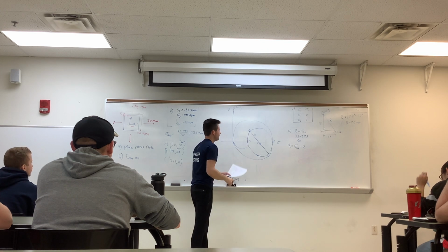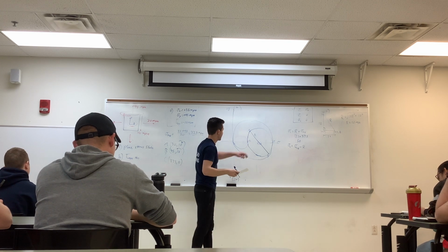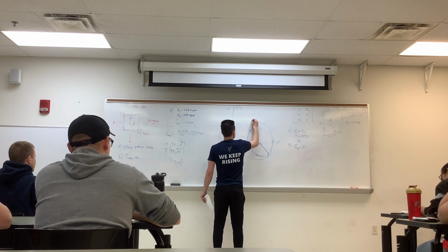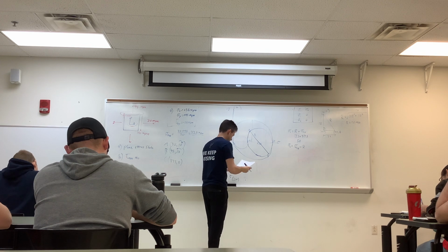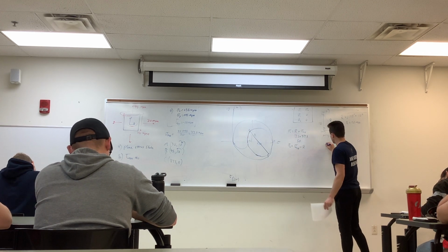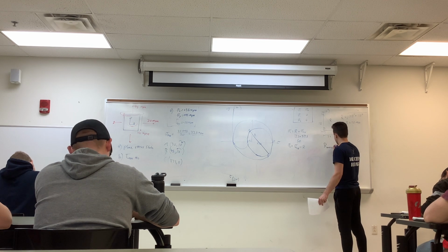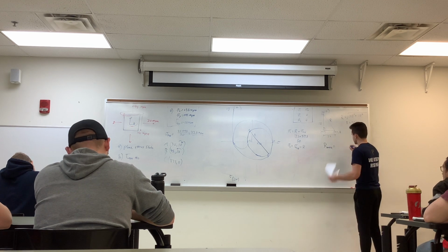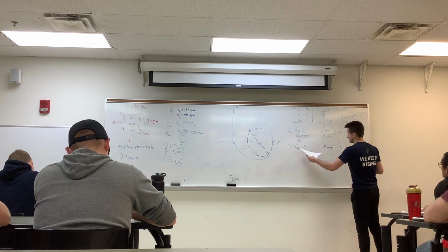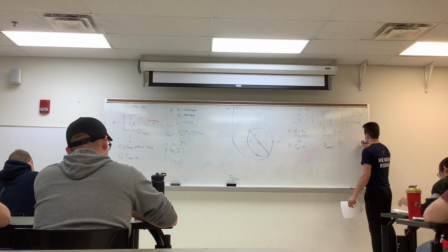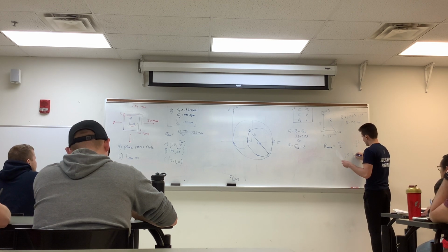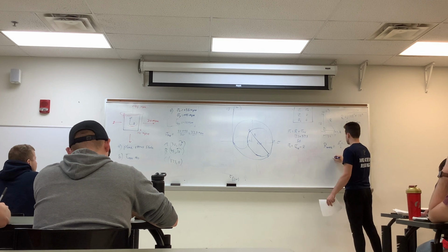Our absolute max isn't actually within the original Mohr circle we have. It is this large one, which makes it out of plane here. So we can find our max radius, or our max tau, to be equal to sigma 1 over 2, so just 50 divided by 2, giving us 25 MPa, which equals our tau.